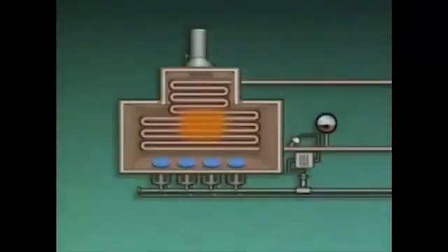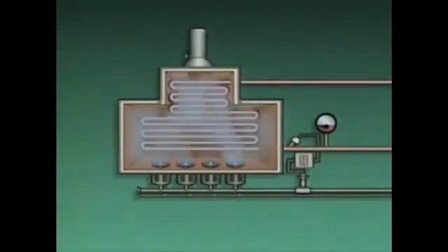In addition, the positive pressure may cause flames to shoot out of the edges of the peephole doors or other furnace openings. Also, the igniting of fuel away from the burners may produce a pulsing or thumping sound. If this airflow problem is not corrected, the burner flames could go out. Eventually, there may be so much fuel built up inside the furnace that if there is an ignition, it could literally blow the entire furnace apart.